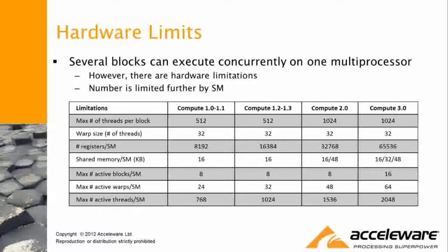So what you'll do when you compile, let's say I have a very basic kernel, and my very basic kernel uses 40 registers, let's say. Okay, so that's fine. So now I launch a thread block of 1,024 threads. So 40 registers times 1,024, I'm already at 40,000 registers, and I only have 1 thread block on my GPU.